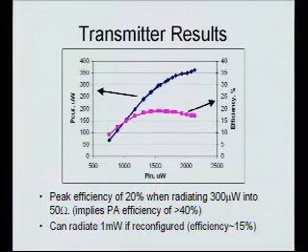And that's, if you get into the low power radio world, you find this a lot, that at the high performance end, typically when people want to make their transmitters low power, they just focus on the PA, because the PA is everything. If you make the PA 5% more efficient, your radio is almost 5% more efficient. But once you get to the lower power regime, you can always make PAs that are at least 40 or 50% efficient. It's just not that hard. But then all the other stuff starts appearing as important, and it becomes a real challenge to get your oscillator to be really low power, and to get your PLL to be really low power, and any buffering you have down. So it's kind of a funny, different regime where the most important power things are not your actual PA, but other stuff.